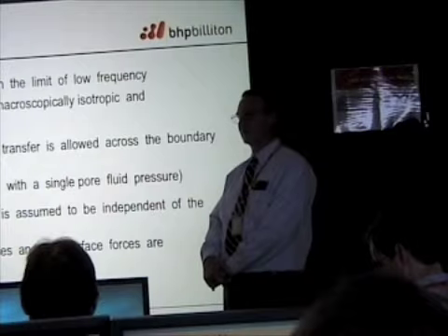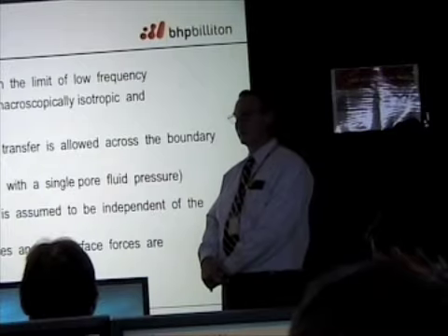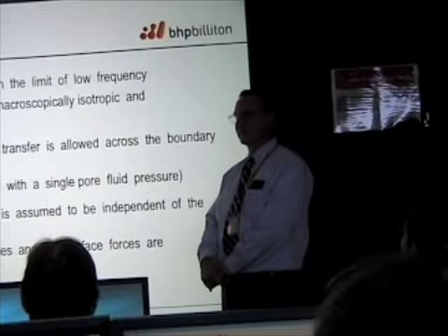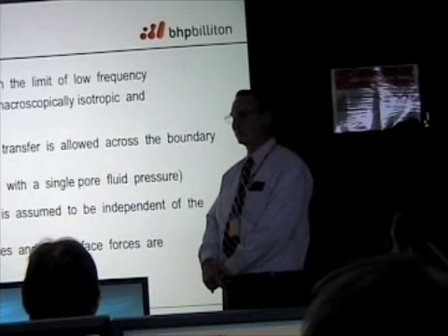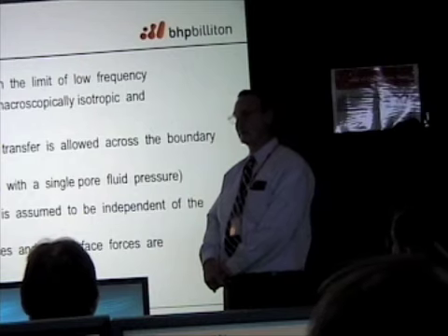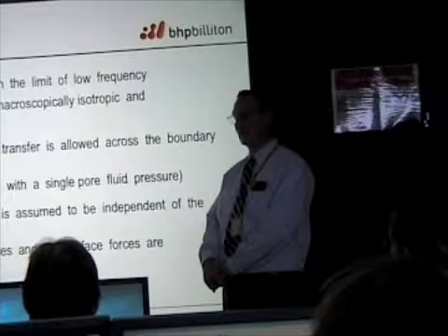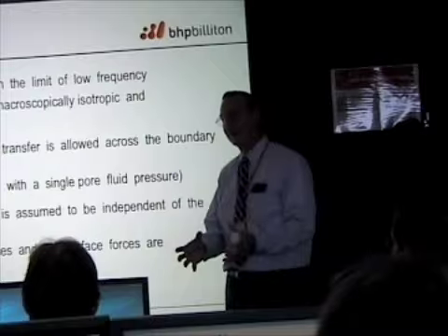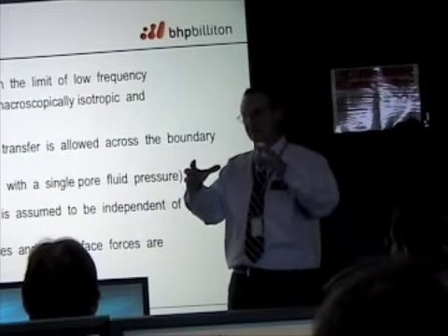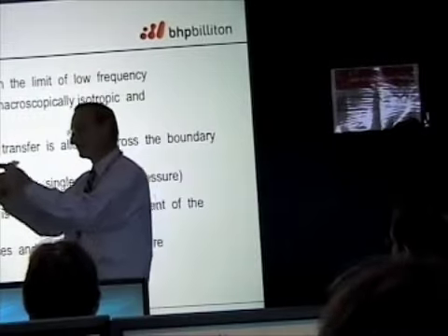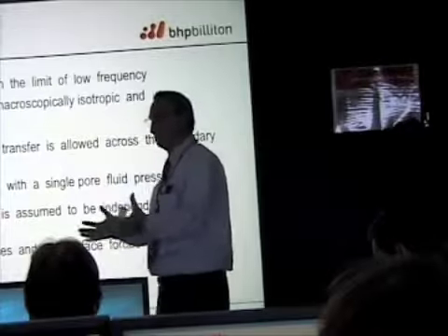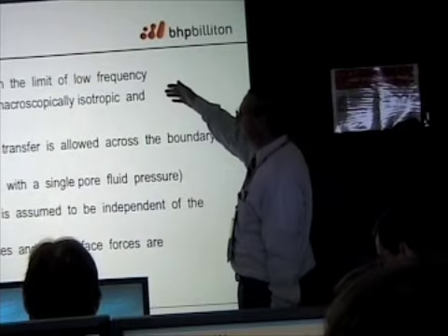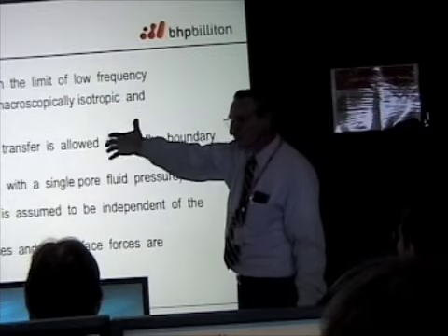100 hertz is a period of 10 milliseconds. 10,000 feet per second is 10 feet per millisecond. So 10 times 10 is a 100 foot wavelength. So I could volume average over a 10 foot by 10 foot block if I want, and so long as this 10-foot block looks like that 10-foot block, looks like that 10-foot block, I'm still okay. All right, and that isn't strictly true.